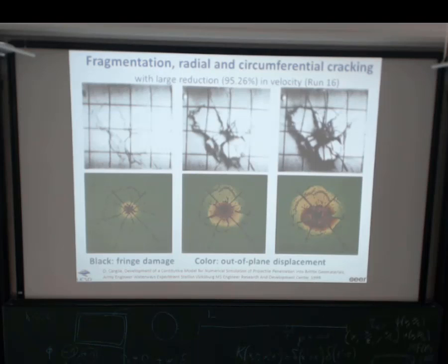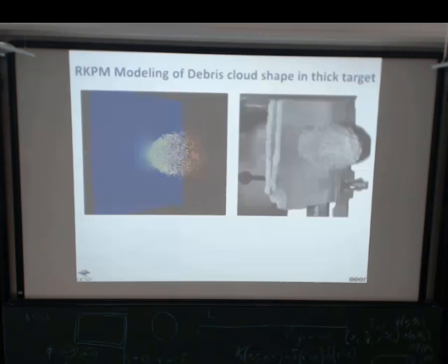The microstructure is pre-computed, and then you use the law. Each RKPM particle, is it just one for the material, and then you use the same curve for every one? So you can, it depends on the approach. You can take different samples from different locations, characterize different damage laws and assign them to different material points. Yes, that will be the more ideal case. But here, no, we just use the same damage law for the whole domain.